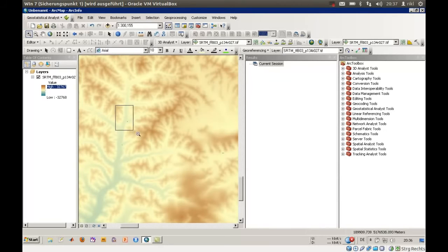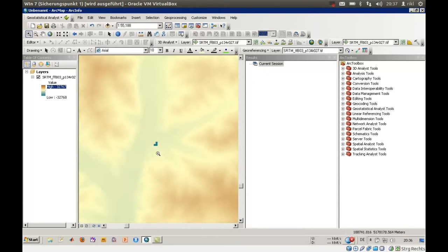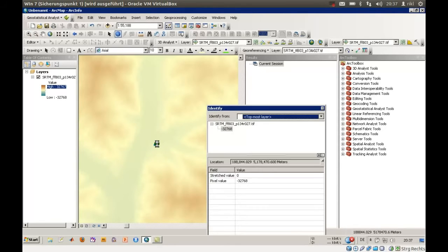things in that. So let's have a look at that tiny spot here. This is a place where no data is available. There are several reasons why there's no data available. It's some kind of shadowing effect, especially in mountainous regions, then some scattering where the beam which was reflected does not put enough energy to the sensor. So it could be that there are these kinds of spots in your SRTM scene.